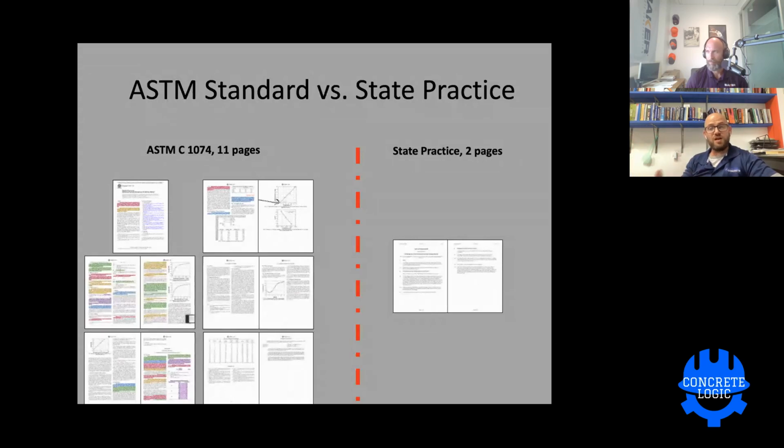But if you don't know what the stages of hydration are, I recommend one of his cement hydration theaters, and I think there's 2 of them. But the later stages, the deceleration and then the plateau, stages 4 and 5, we can't really see those. The exothermic reactions are so low, and the rate of temperature change we get from the ambient environment is so great at that point that we have no clue how to use that to estimate it. There's just no way to estimate. It's not that we have no clue, it's just too random to estimate based off of those temperatures. Does that make sense? Yep.